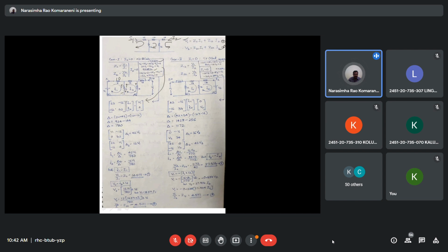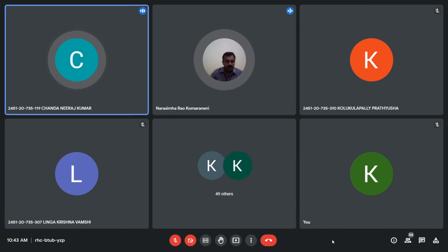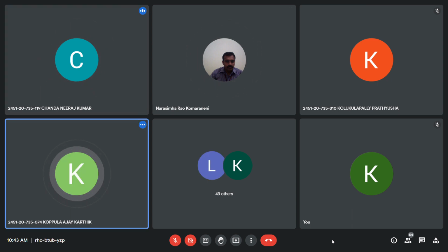Now find the delta value, and to find this I1 value, you need to find delta 1. After finding delta 1, I1 equal to delta 1 by delta gives the I1 value. Similarly, to get the I2 value, find the delta 2 value, and delta 2 by delta is nothing but I2. And one more thing, if you see here in the first loop, this capital I presentation.